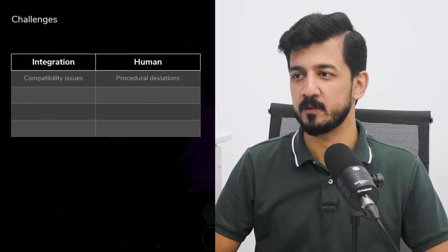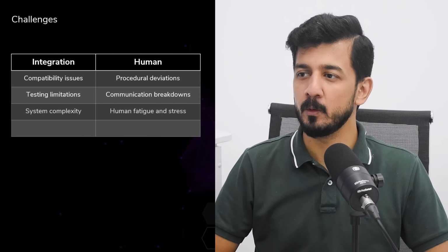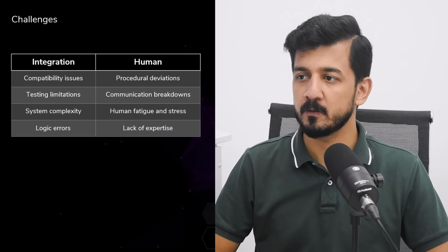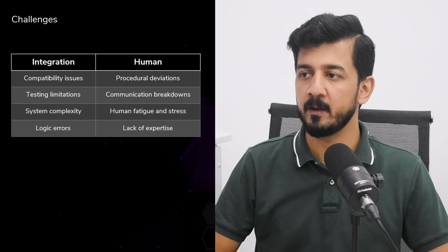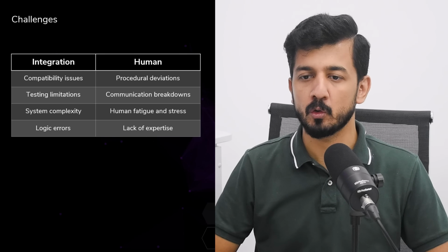Most of them are from the point of view of integration, and some of them are from the human point of view. As far as the integration is concerned, just like I said before, you need to test your architecture thoroughly. Then another thing you need to make sure of is that your operational test procedures are simple and easily understandable, so you can quickly test all the functions offshore as intended by the safety system.